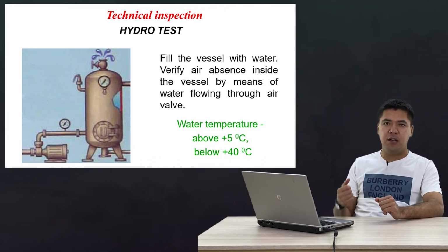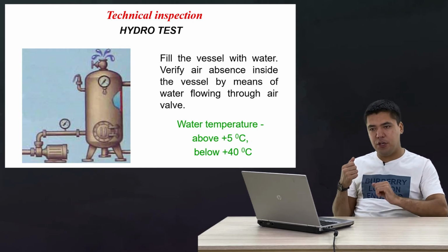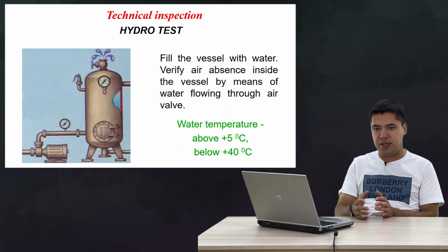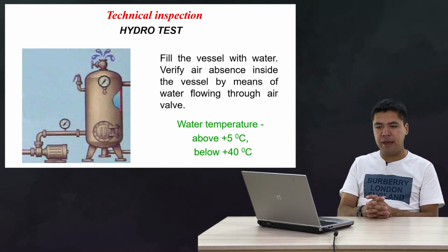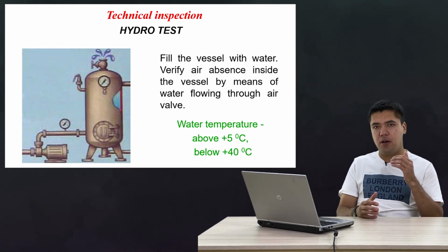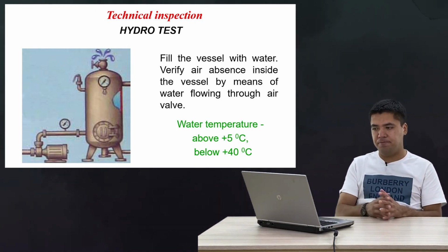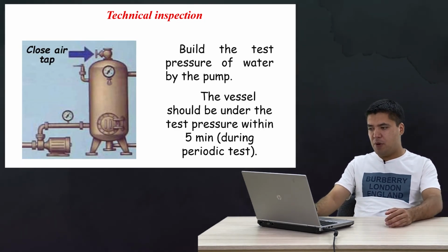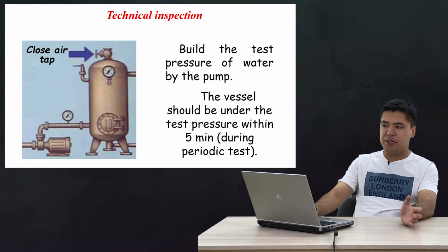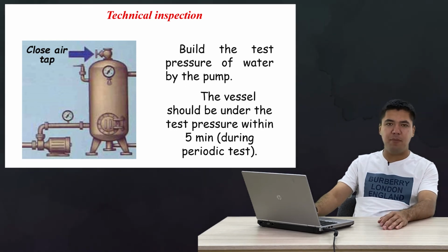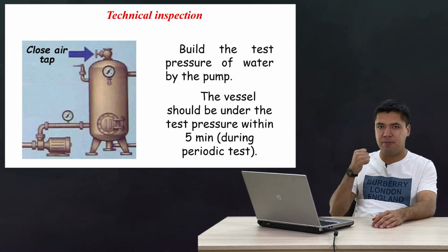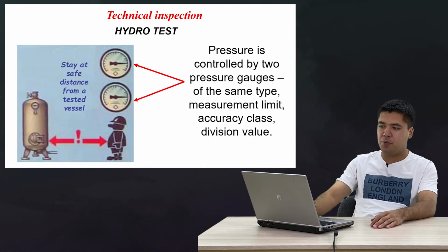In that case, within negotiation with expert organizations, hydro test can be performed by adding different chemicals to give anti-freezing property to the water for performing a hydraulic test. And about the hydro test, build the test pressure of water by the pump gradually, not just directly. We shall not do it. It can be very dangerous to operational personnel.